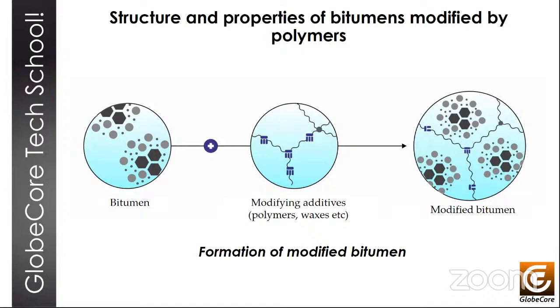And depending on the ratio and chemical structure of the components of the dispersed phase and the dispersion medium, a certain spatial structure of asphaltenes and a swollen polymer network, a lattice, is formed above a certain critical concentration of the polymer, the critical concentration of structure formation. This structure can be a special lattice of polymer within the coagulation framework of asphaltenes, or a spatial network of asphaltenes and polymer. And these polymer structures impart their mechanical and rheological properties to the original bitumen.